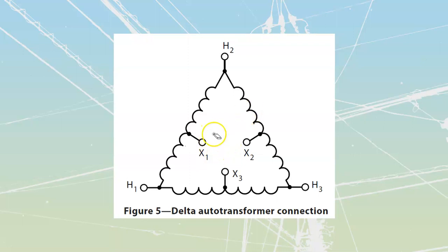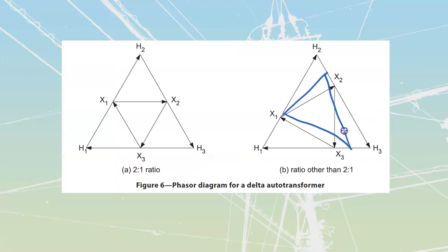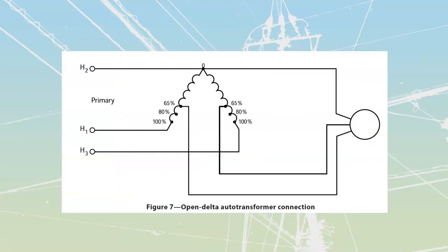And as I rotate that triangle through the inside of the Delta Autotransformer, it's always changing where those different phases are going to be at, where it's A phase, B phase, C phase, because that triangle is rotating through on the inside. With the open delta autotransformer, we get this advantage in that we are just taking a triangle and starting with that triangle up here in this corner, and we're just making this triangle bigger and bigger and bigger by attaching across different sets of taps. And that's going to allow us to maintain our A, B, and C phases in the proper order.